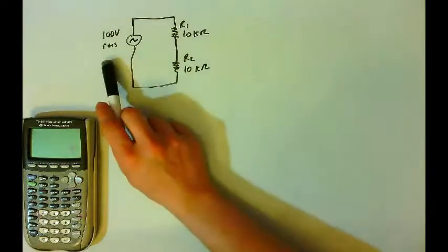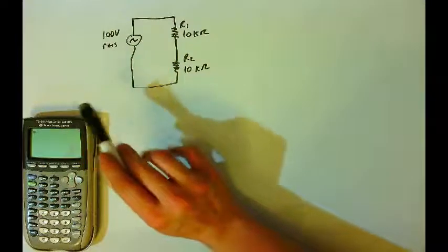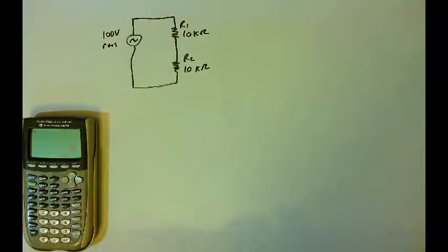Now the voltage was already given to us in RMS. We are almost always wanting the RMS value when we're looking at AC circuits, because the RMS value tells us the value of the voltage of an equivalent DC circuit that has the same power dissipation effects in the circuit. And so the peak voltage of 100 volts RMS would be 141.4 volts. We're almost never interested in the peak voltage, almost always in the RMS voltage.